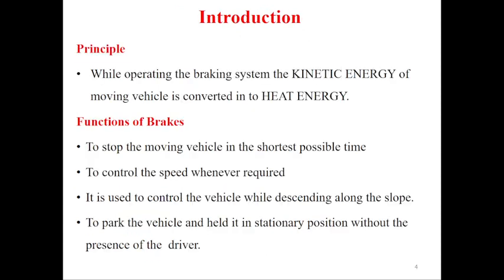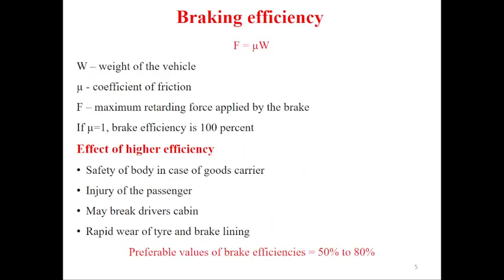Now calculating the braking efficiency: the maximum retarding force is equal to the coefficient of friction multiplied by the weight of the vehicle.